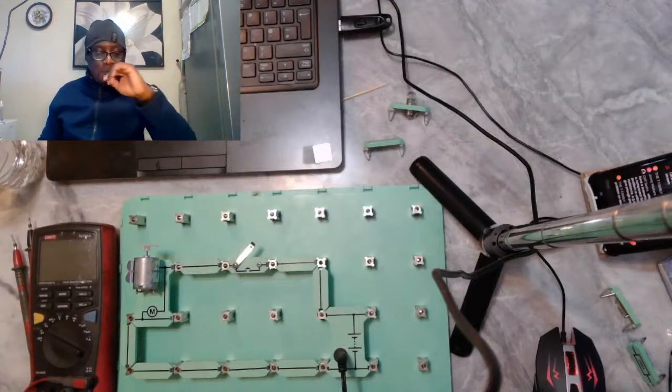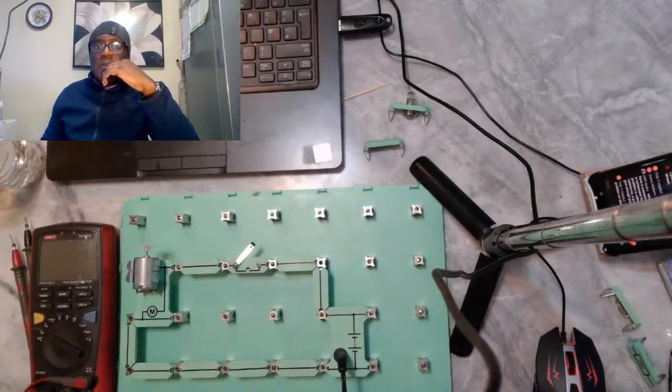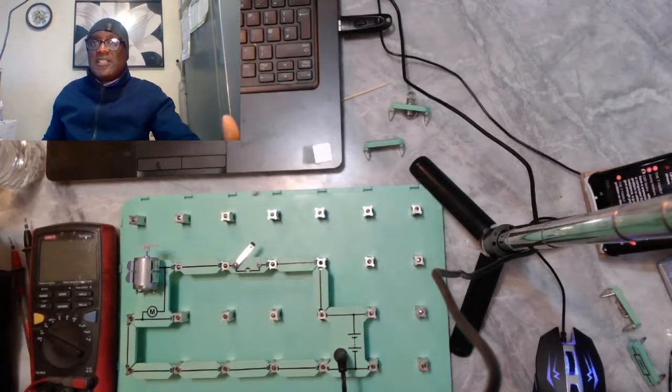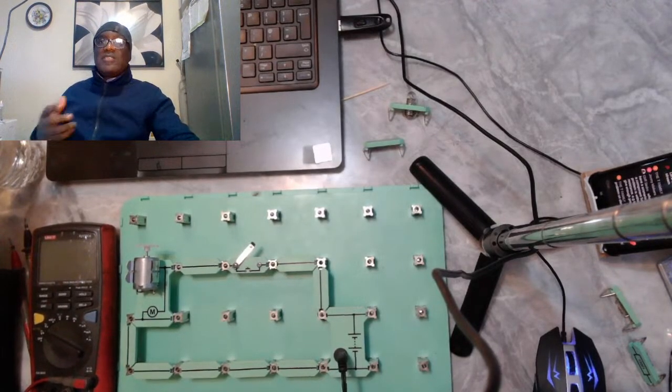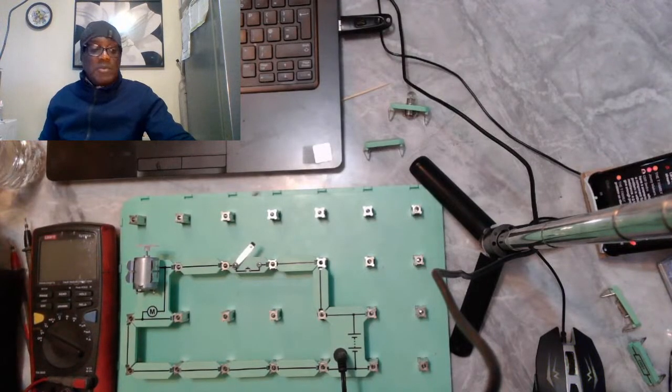And gentlemen, Cliff, you're right. I agree with you. Someone once encountered a problem on an electric mirror switch. I'm actually fixing one at the moment. I've got a Volvo where one mirror folds in, the other one doesn't. You can tell that the power is there, so I think there's an issue, seems to be high resistance.